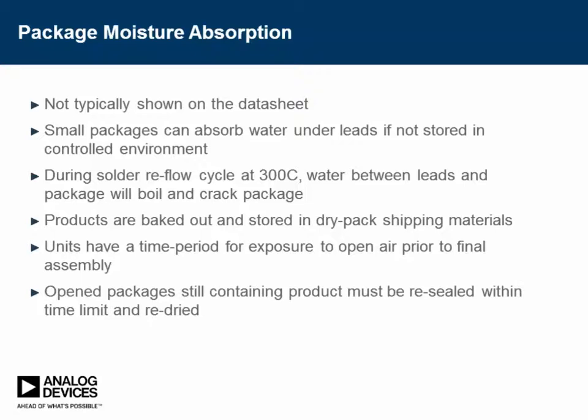And then of course, you have to take them out of the bag to run them through assembly, and there's a time period, and that's determined by the moisture level rating for the product. And everything that's been opened and hasn't been used needs to be put back into the dry pack. Once the device has been assembled and has gone through the solder reflow cycle, then it's going to be okay, because you're not going to have it up at 300 degrees C again after that.